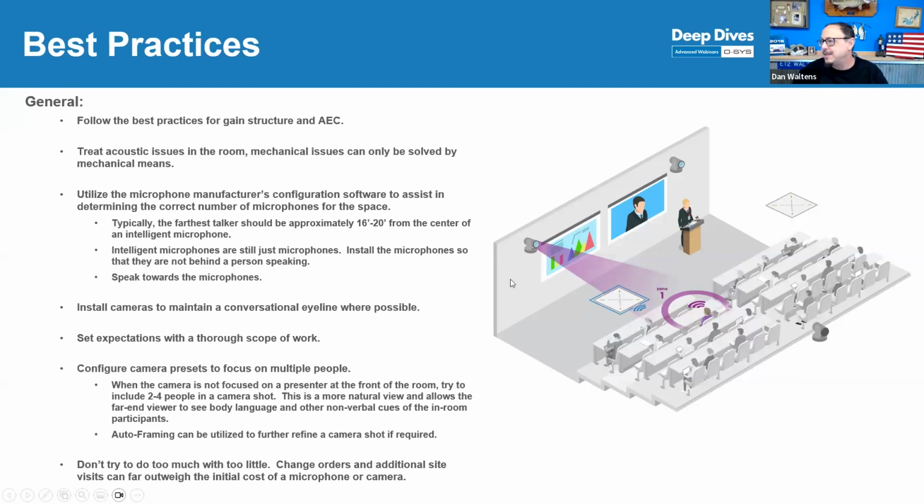You'll notice that in this case, these are up high because of that. That is one of my frustrations when I go into a conference room and the displays are 48 inches off the floor, and then the cameras are up above it like this. Nobody likes to be in a conference that looks like this. So try to always remember to bring those cameras down, below the displays. I had one customer before I came to work at Q-SYS who liked their displays a little lower, so they would spread them apart and put their conferencing cameras in the middle. So that's an option as well. Primary and secondary cameras, we continuously show them side by side, but they can be stacked on top of each other as well, if that's what you want to do.